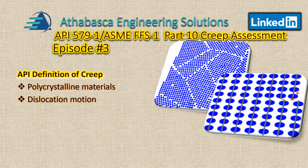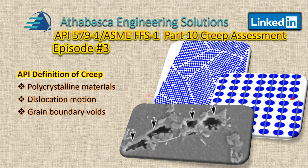When a material is under stress, and especially at higher temperature, dislocations can travel more easily. These dislocations or imperfections migrate to the grain boundary and create voids, like that shown in the diagram here. You can see the voids here and here. Basically, this reduces the strain hardening ability of the material.